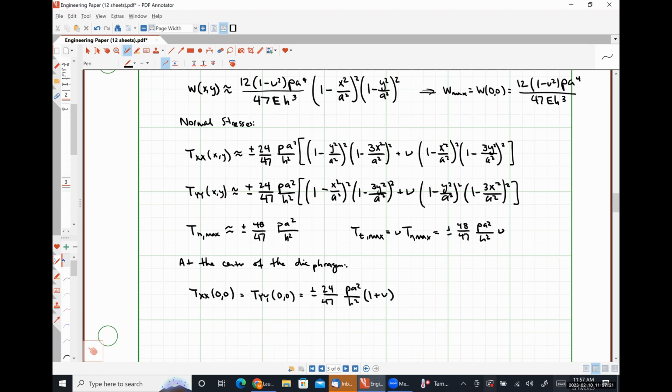So, all right. Like I said, we're not going to do rectangular membranes because the math is just absolutely horrifying. They do behave pretty similar to square membranes. We're also not going to do any mathematical work with a capacitive pressure sensor because once again, the math is horrifying because we have a non-parallel plate capacitance. For small deflections it's going to involve a double integral and the use of a Taylor series expansion, and it gets worse if the deflection is larger. So we're going to look at piezo resistors because the math is not horrifying there.